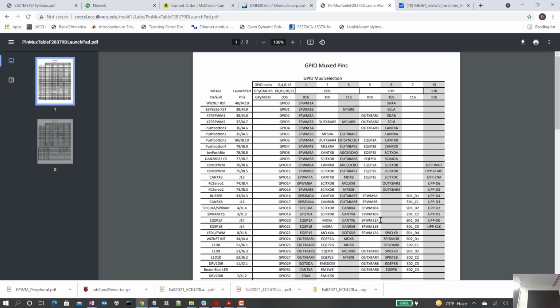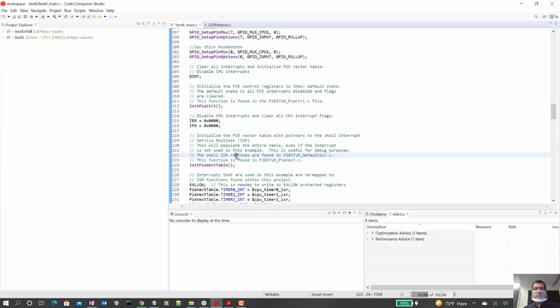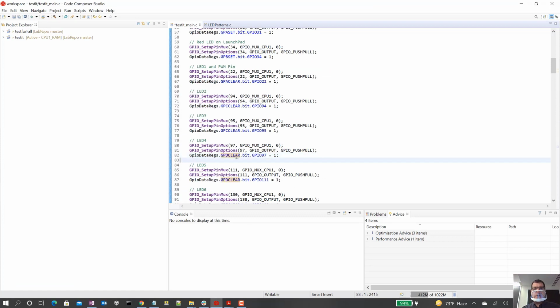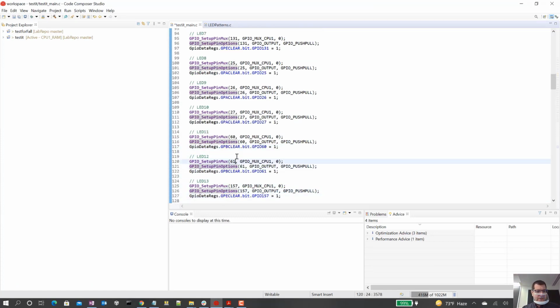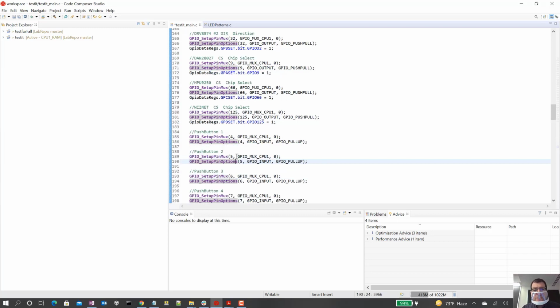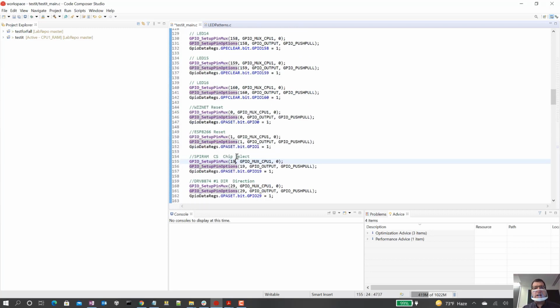Anyway, okay. So your job will be to figure out what mode, what MUX state your pin will need to be in. So if you go to our C code, beginning C code, you'll notice that all these lines of code here, I am setting up right here the PinMux. We have a bunch of them. A lot of these are our LEDs, but you'll notice, let's see, do I have any of them? No, they're all set up right now as LEDs.